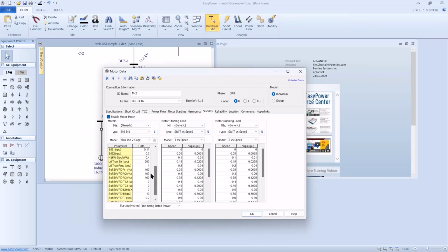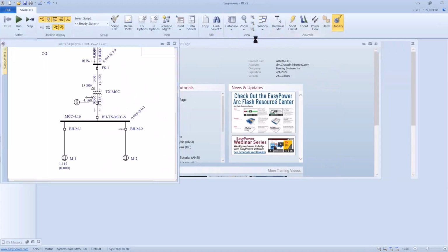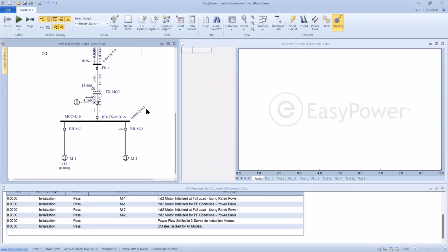And now, let's say for soft start, rather than going to 100% across the line, initially we go to 25% and then to 70%. We stay in each condition for 1 second, just winging it. So I set the time to switch at 1 second. And so we'll see a different curve now based upon the motor starting with a soft start. Again, I'm just winging this. This is not the way you probably need to do it, but I'm trying to show the merit of the capabilities.